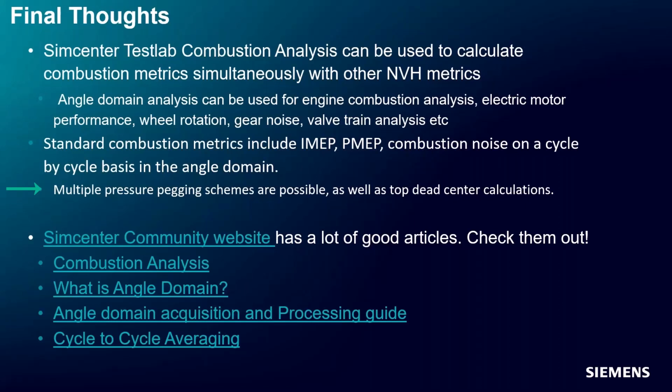And the pegging schemes, like based on the polytropic coefficient, or using a known reference value, or based on a reference channel that you have measured, all those options are available in the combustion analysis module. That's what makes it very unique in terms of the Testlab combustion analysis. You can do it all in one package: the standard NVH metrics as well as the combustion metrics.